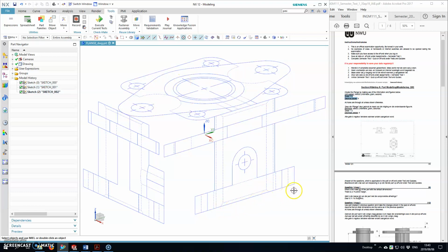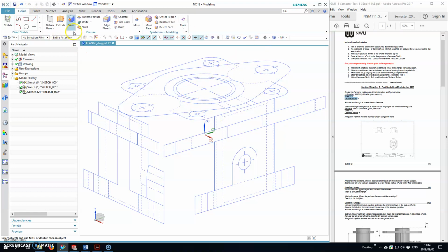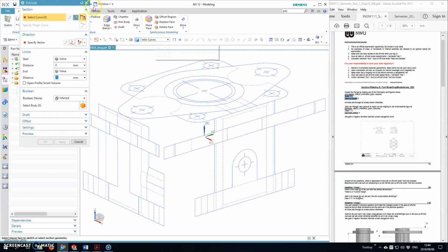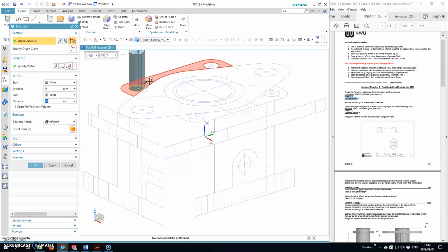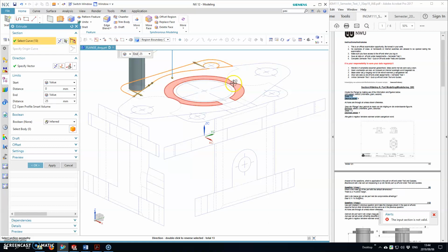So basically build a base, and then from there extrude this section, then that section, and then of course all the radius and all the holes and stuff that will be created on the last step. So on the extrude, we can change our filters to region and boundaries. Then we can select certain regions that we want to extrude, right?